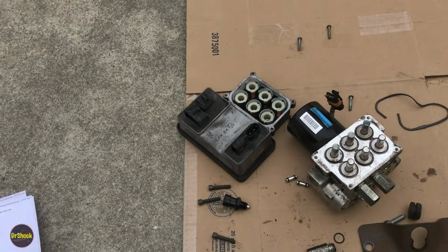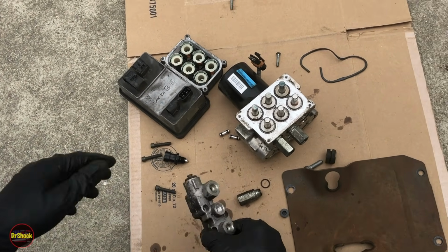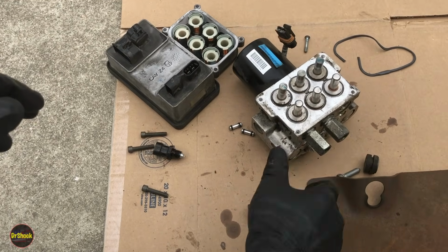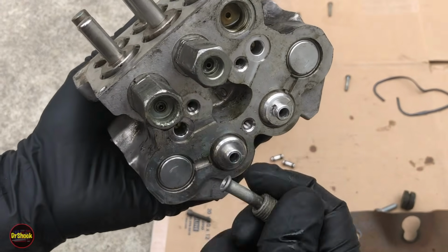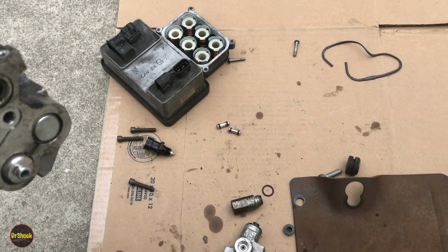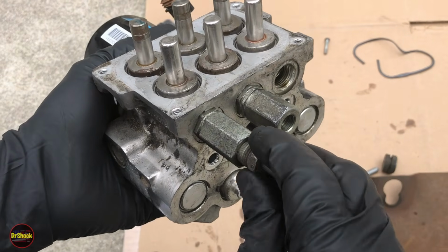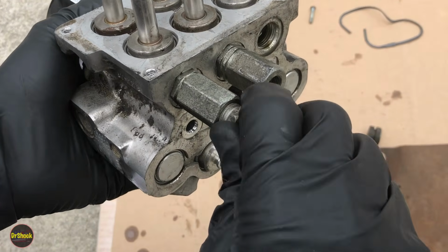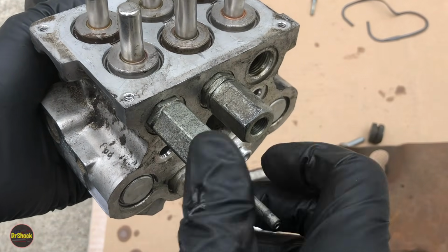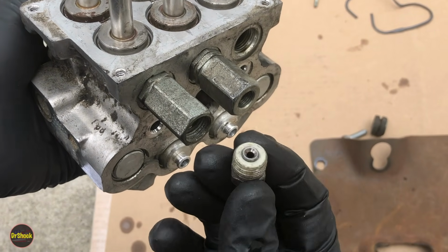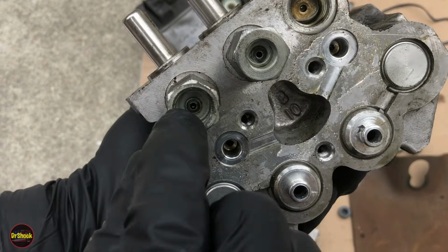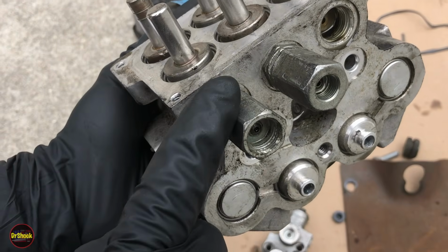So the last thing I'm going to show you is a little bit about mounting this stuff. Sometimes, actually, I'll show you on this. This is a better example. Let me see if I got the right one here. I want to get one of these that fits one of these guys here. Sometimes you'll get weep leaks through here. The reason you get those when you put this back together is typically because somebody has overtightened the fitting. So it's either damaged the flare on the stainless hardline or it's damaged the seat. That's the whole reason these are replaceable.